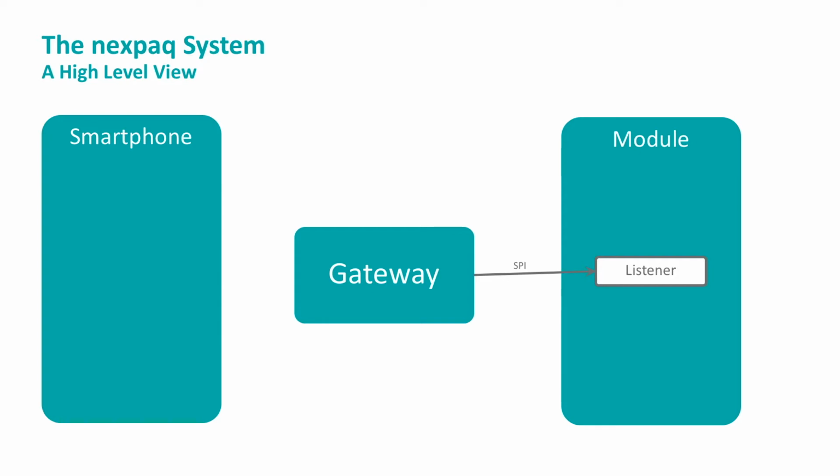In our application, the main loop runs once per second. When the main loop runs, it calls a routine that gathers information about all the pins on the device and transmits the status message via the gateway to the smartphone. When the smartphone receives the message, JavaScript code running in the nexpaq application parses the data and changes the state of the indicators on the smartphone screen.